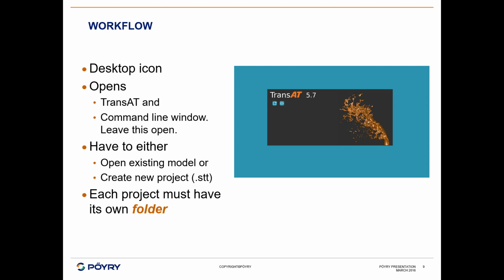It's very important that each project is saved in its own folder without any other project files in the same folder. You could have a sub-project as its own folder inside another project folder, but it's important to keep STT, INP, and other TransAT-related files separate from other projects.